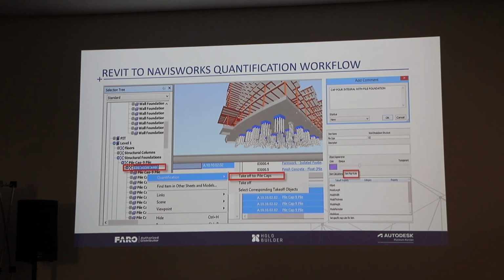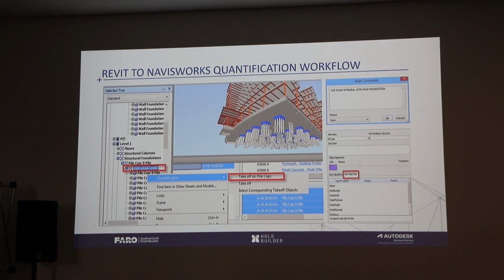Now with Navisworks, it's quite easy to calculate the 5D timeline, as all you'd have to do is import the Revit model into Navisworks, as long as the model is quantified correctly within Revit from the schedules. Once you put it into Navisworks, it will immediately quantify all the elements within the 3D model and input it into a schedule aligned with the costs, which can be exported into Excel, where the quantity surveyor can now total up the costs of everything.